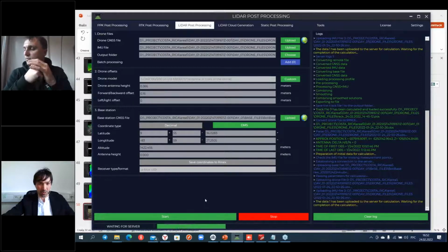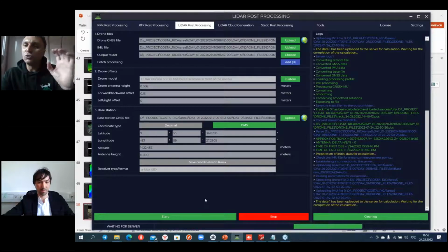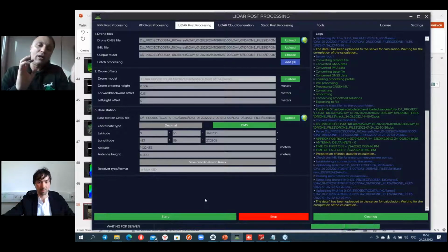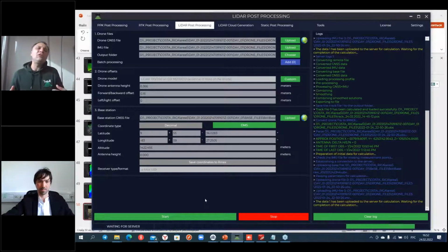One question which is directly connected with the LiDAR is: how many returns of the HDL LiDAR do you get? Two returns, the strongest return and the last return, and all Velodyne sensors provide two returns. Livox sensors provide three returns. But don't consider these options.